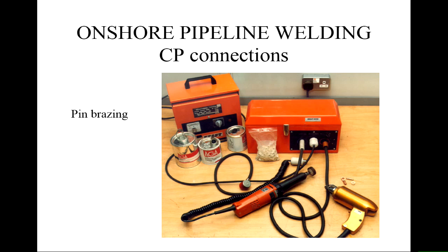There's also the necessary cleanliness, so there's a little grinder to grind an area where we put that pin there. So that can be used for making attachments. There are percussion systems which do that just with a big voltage drop. There's a whole range of different portable technologies that enable you to put a small connection, a bolt, onto the surface. And you could choose any one of those really to do things.